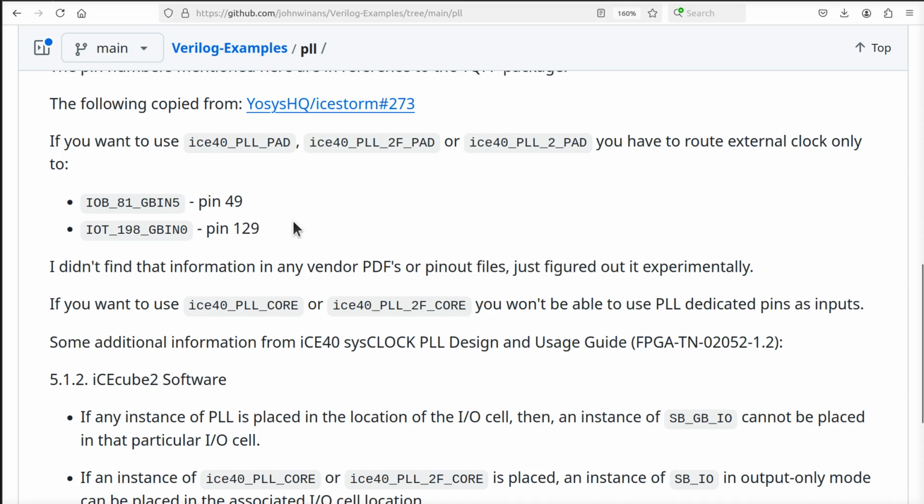Any other pin, you end up with the problem that I have right now, and that is I can still build circuits and it works fine, but you waste 1 LUT because you're not able to connect the input clock directly to the PLL. All right, so it's a little bit embarrassing. I have not verified this. I have verified this. Okay, we can do a quick test. We can't see it run on my board because I don't have an oscillator hooked up to this pin. We could rig one up, I suppose. But there's another way to do it.